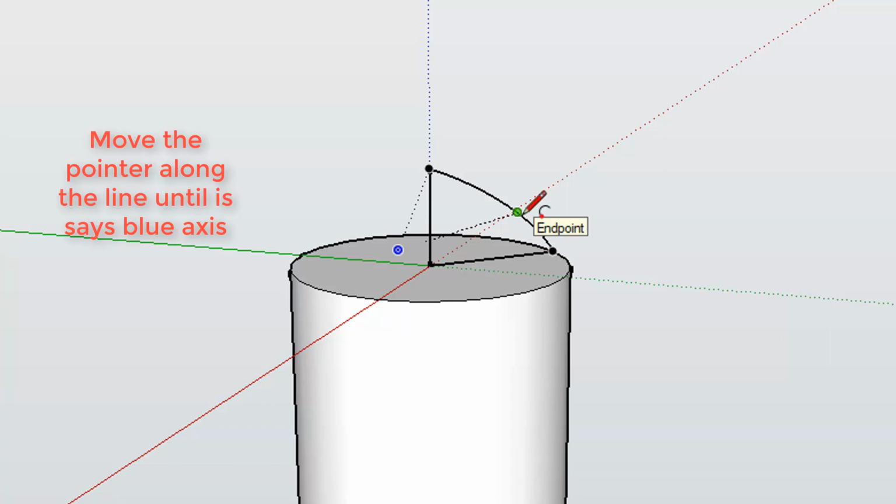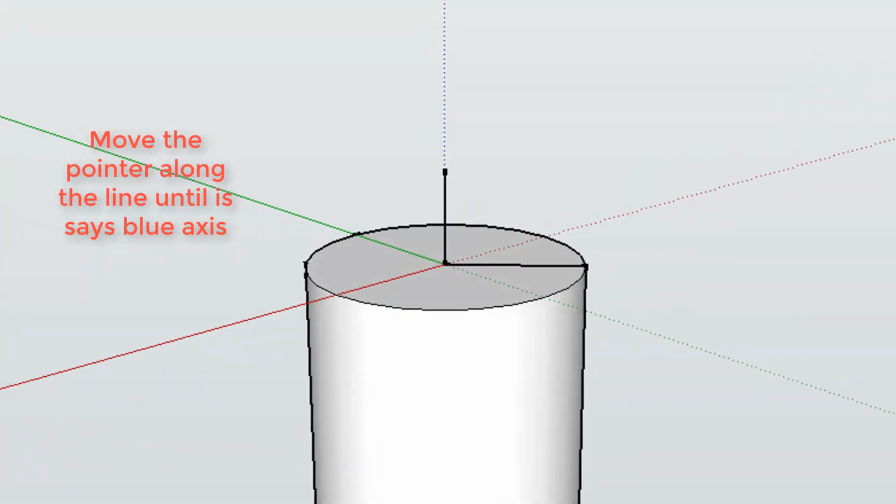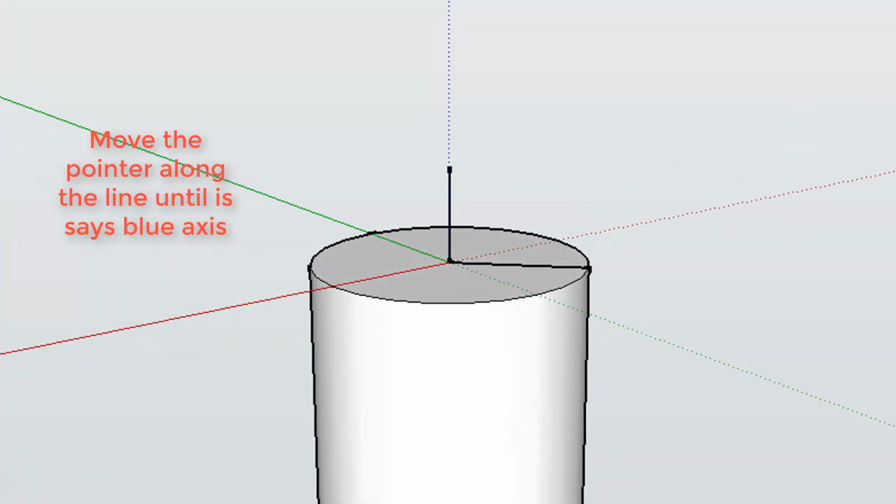So you see it didn't fill in. If it didn't fill in, it means it didn't work. So you get rid of it, Control Z, get rid of it. Swing it around, try a different view. Once again with the 2-point arc tool, go to the top, go to the bottom. Nope. I'm going to show you why.